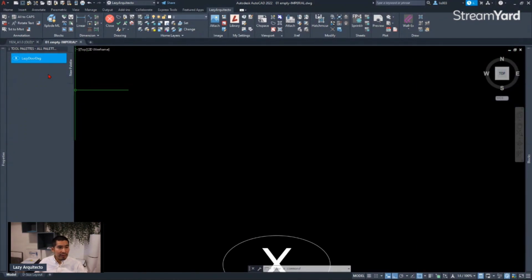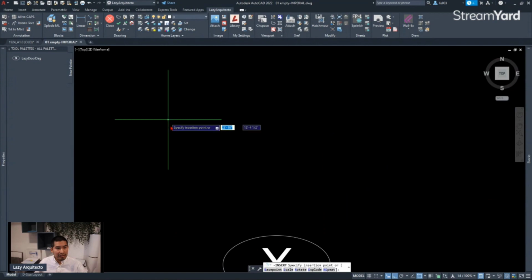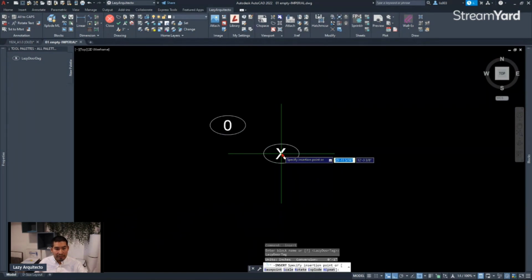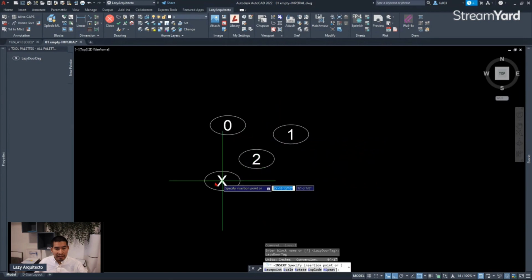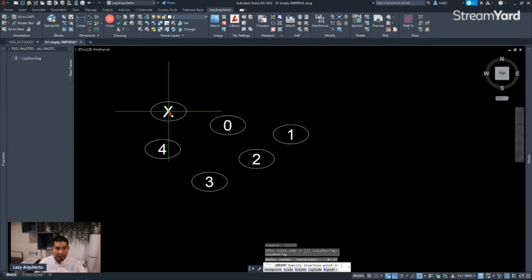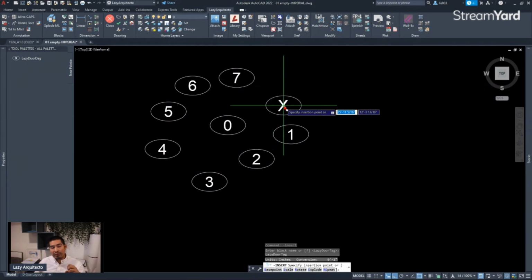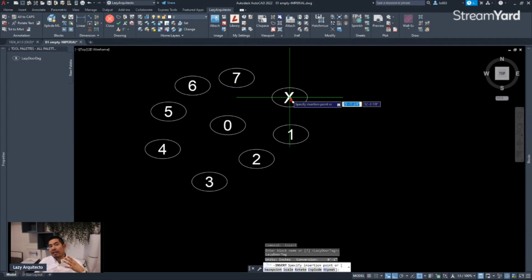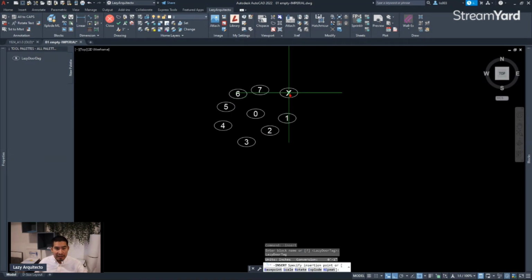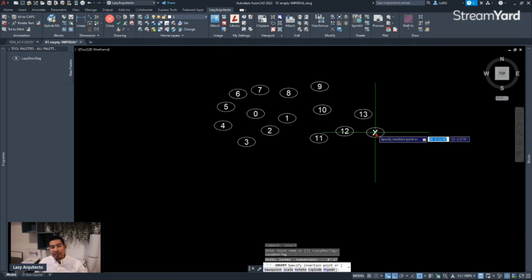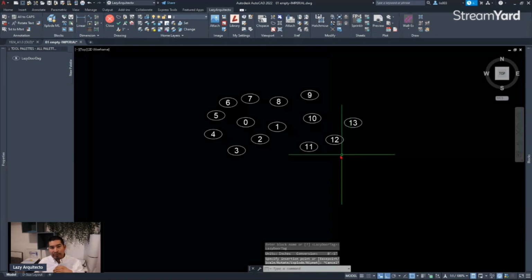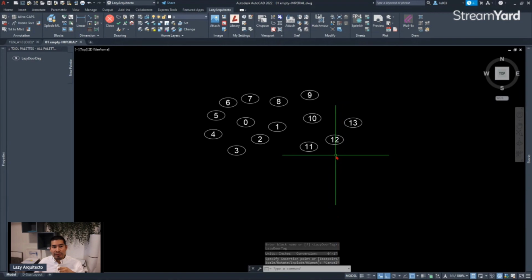So at this point, when we click the door tag, like so, we can see, if we zoom in, that indeed it's working. So now my client could avoid numbering his door tags manually, which is a big help for him because at an office, time is important because time is money also. So now that we knew that the auto numbering for his door tags was working, we proceeded to simplify some of his next steps.